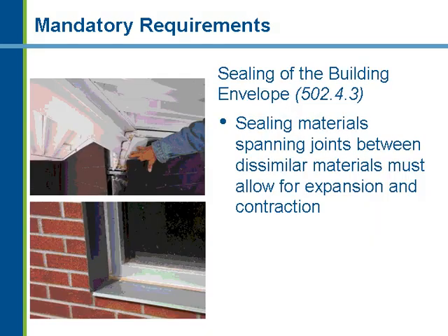A couple of examples, metal building, you can see the framing extending out of the roof system and the foam. The foam that's shown in there is an example of how that would be air sealed. The sealing around windows, as in the bottom picture shows, is a requirement by code. Sealing around doors, but again, any penetration, anytime you can see daylight, it should be sealed up.